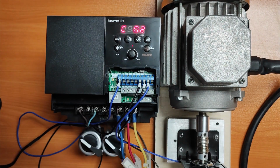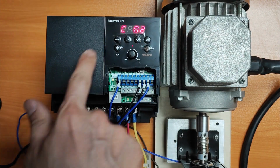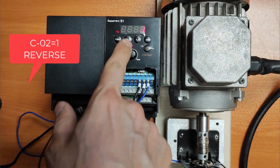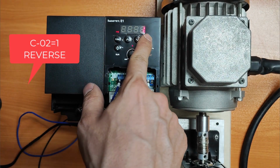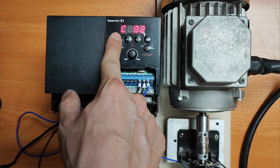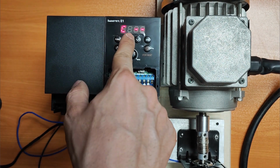But for digital input number 2, we said we want the inverter to start in reverse direction when it's activated. Parameter C02 is directly related to digital input number 2, so let's go ahead and look into it. To properly assign the reverse function to this specific digital input, we will need to set this parameter to the value of 1. Alright, so these are the essential configuration settings we need to make on the E1 inverter.